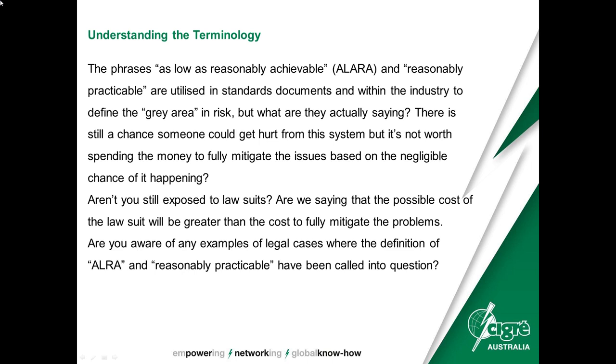Look, I would agree. Let me just say one thing about the traditional voltage criteria. Many people consider them safe touch voltages, and they think that that would mean that if you were exposed to it, you would survive. And I can't say it clearly enough that for every one of those allowable voltages, whether it's from IEEE 80 or from IEC 61936 or from Euronorm 50522, there is still a probability of fatality if you stand there and touch it when the fault happens to occur. So all of our safety criteria, even the traditional voltage criteria, had some level of fibrillation risk, and all of them were relying on there being some level of unlikelihood as to whether you would be there when the fault occurred.